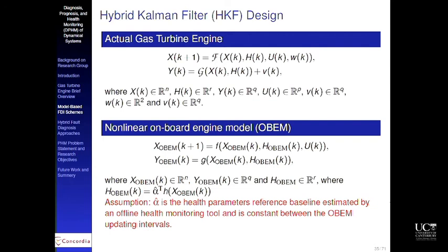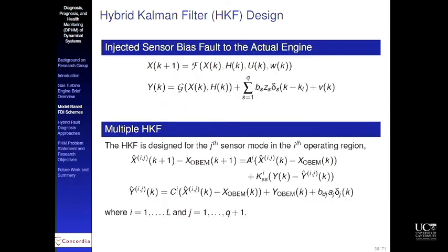So what we have shown, and here is the idea, is that if you take a linear representation of that mathematical model of the engine and apply a linear Kalman filter or linear state observer approach and simply subtract the onboard engine model, which is a nonlinear model of the system, from the estimates that you get from your linear Kalman filter, really significant improvements can happen.